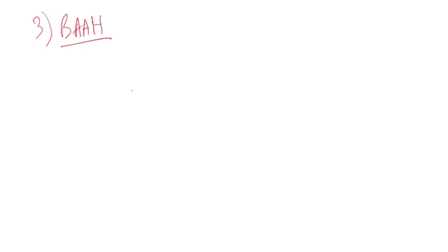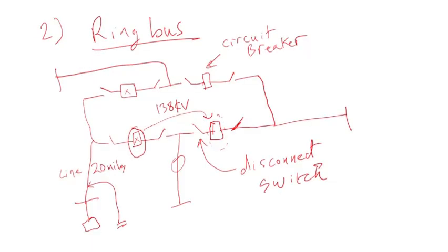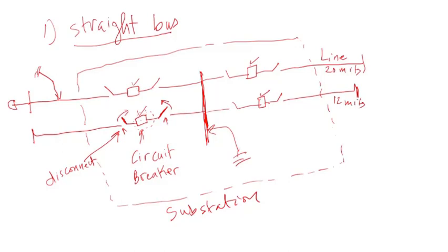Breaker and a half is typically used when you have multiple facilities connected to a bus, more than 5 or 6, probably, and you're going to expand the substation in the future. But since I have only 4 things connected to bus 3, I'll just keep 4, even if this is not practical, because with 4 you would probably want to just do a ring bus.